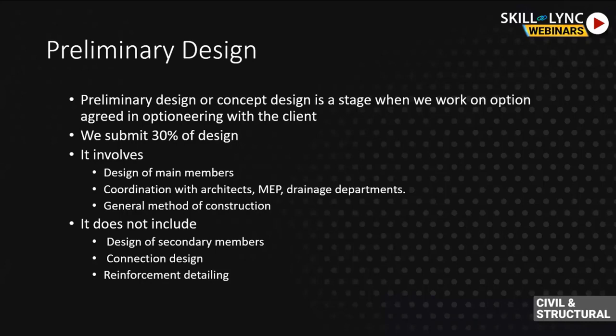And preliminary design also fixes the general method of construction. What will be the lifting capacity of the crane that will be used, where can we mount the crane. So I work with railways. A lot of time you have an existing station that we are working on, and we don't have access to the station. Then what is the place where we can put our crane, how much is the boom of the crane, where it can reach, how much is the capacity of the crane at that angle that it can lift.